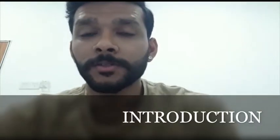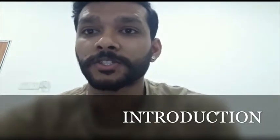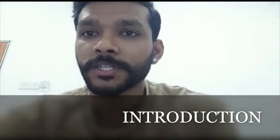Hi, I'm Gajendran here. Today we'll be talking about the process for production of styrene. The main objective of this process is to develop styrene as the final product from ethyl benzene, as well as to obtain a final product purity of a minimum of 99.7 weight percent, taking into consideration the economic and environmental aspects. Lastly, the objective is to have a production capacity of 250,000 tons per annum.